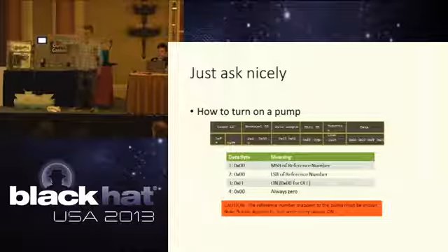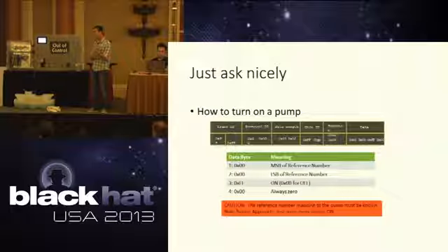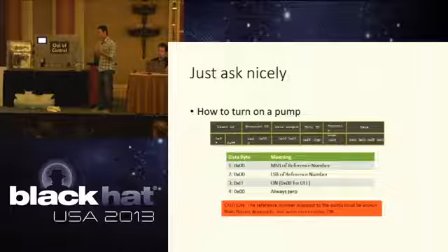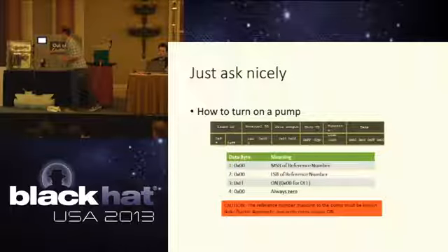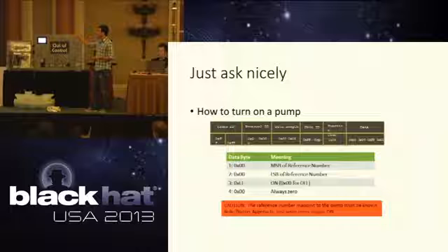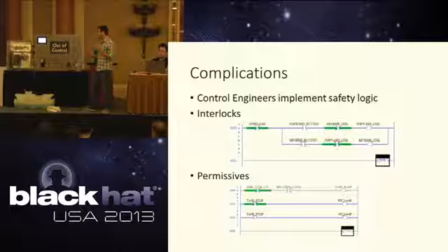So we have this word of caution down here, because Modbus is a really, really ancient protocol. There's not really a way to know what you're driving. All you know is the reference number. So unless you get on an engineering workstation and find the mapping that maps a reference number to a physical piece of equipment, you don't know what you're actually driving. But sometimes you just don't care, right? Sometimes the reference number is in a very specific part of addressable memory. So what you can do is just do the nuke option, just turn them all on. And we can do that, and we will do that, and see what happens.